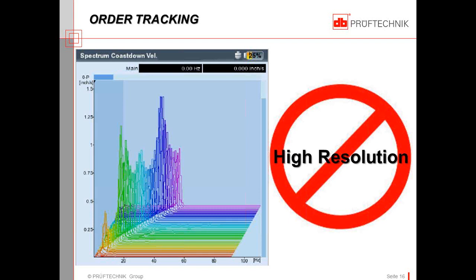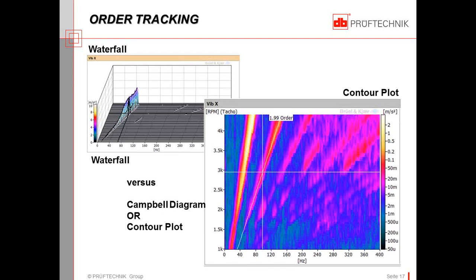We're trying to look at resonances. If we were in a classroom environment, I might ask you the question of how would resonances appear on this waterfall plot? Well, what they would typically appear as is straight lines, whereas the harmonic data would appear as 1x, 2x, 3x fanning out from the